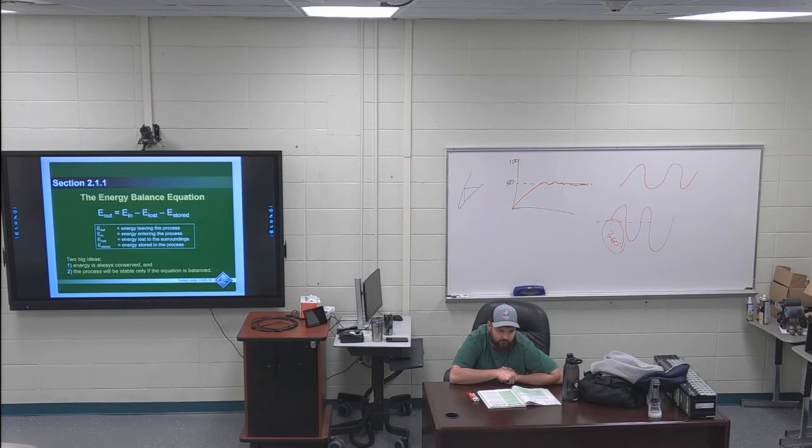We used to have to, y'all ever gotten to the math where you have to do integrals and derivatives and stuff? They made us do that in college to figure out the actual number. You could do integrals and derivatives to find what your gain is, and that's literally how that math works, but it was difficult. It was a lot easier to do trial and error to see. I mean, that's part of the engineering side, to mathematically know what you're supposed to set it to, but it was definitely easier just to change your gain and see what works smoothly, depending on your circuit.